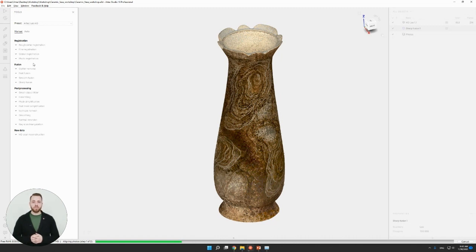Yeah, so once the registration is finished, just like with our scans in Artec Studio, we'll be able to assess the error. So a particular error parameter or error number will be assigned to the photo set that we used. The numbers that you will be getting vary from 0 to, I would say, about 10. But if it reaches 10, then you've got a serious problem. Generally, the range that we prefer to operate within is from 0 to 3.5. If you've got the registration quality within those limits, then you should be okay with your final texture.